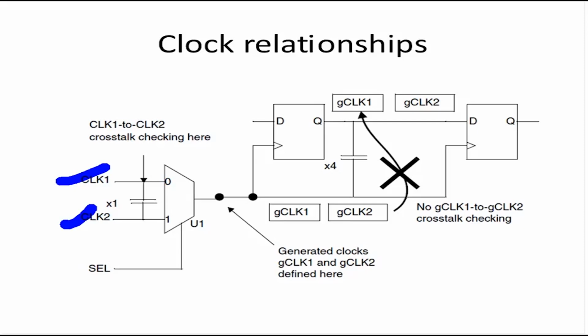But the gist is the clock relationships. I'll just summarize this. The clock relationships are very important for noise and crosstalk delay calculation. If you are doing noise and crosstalk delay calculation, use the set_clock_groups command. Third important point: be very sure about whether the clocks are logically exclusive or physically exclusive. Actually, I should have a summary slide here. I'll probably add this later.